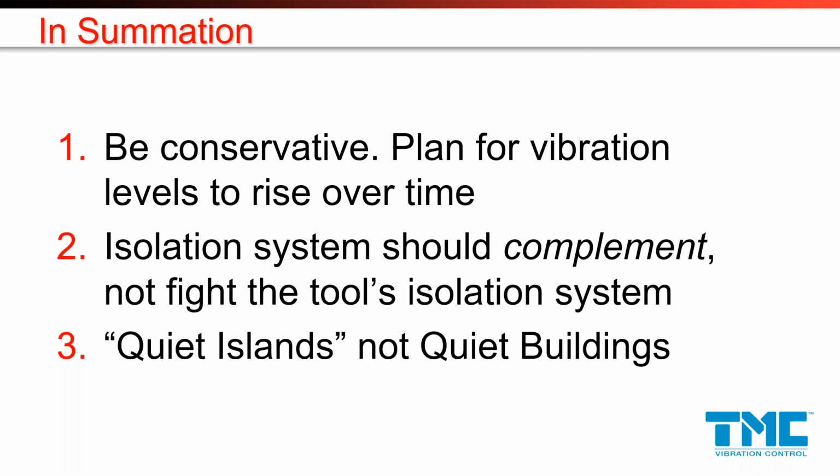So an accelerometer is going to give you much better information at 100 hertz. But if you're measuring down to sub-hertz, it takes an extremely sophisticated accelerometer to measure anything at those very low frequencies, whereas velocity sensors pick that up much more easily. So just in summation, we use velocity sensors rather than accelerometers because they're more sensitive at the low frequencies. And if you can't measure it, you can't cancel it.